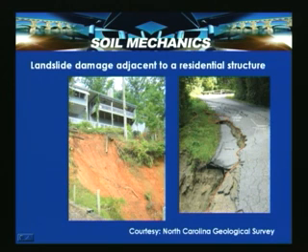You can see here there is a structure or a building very close to that, and the slope surrounding it fails. So, the building at the crest of the slope can be subjected to distress because of the slope failure, which can induce failure or overtopping of the building also. In this case, a road subsidence was caused, and that portion of the road has failed, as shown, and the cracks development can be noted in the picture on the right hand side of this slide.